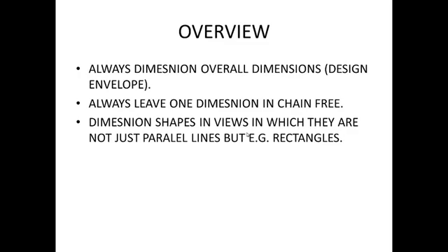And dimension shapes in views in which they are not just parallel lines. For example, when you see a rectangle shape, you should put dimensions exactly there, in the view where you would be able to see these rectangles.